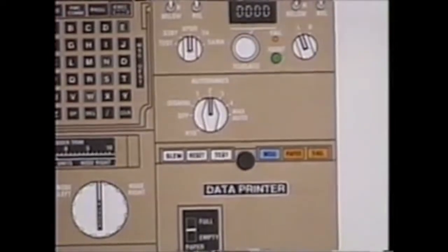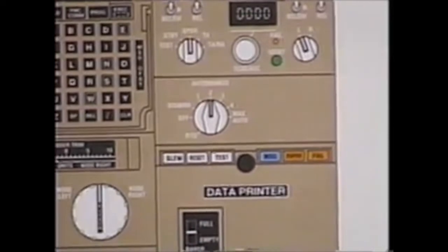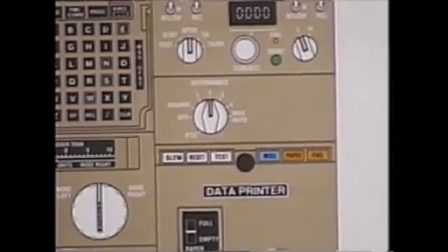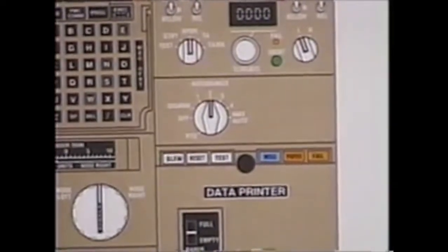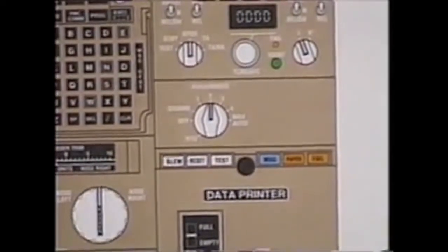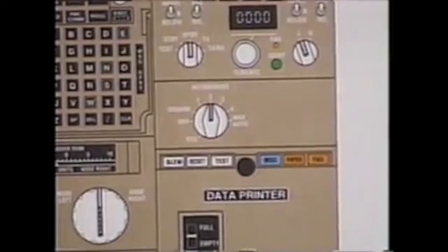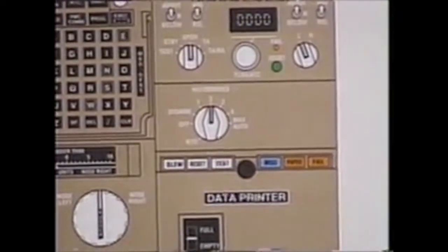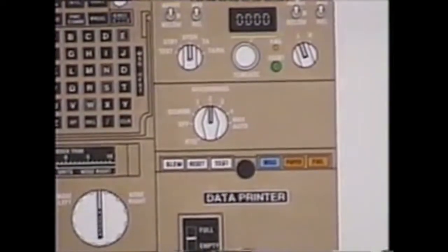You will get max braking to a complete stop if you do not disarm RTO. RTO will not factor in reverse thrust. RTO does not compute a deceleration rate. It allows max braking to occur to a complete stop. You cannot physically outbrake RTO.